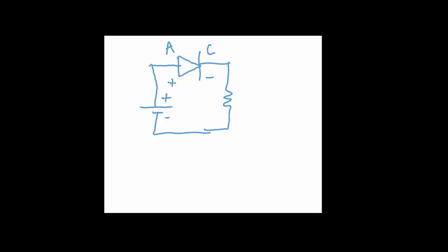The diode will conduct only when it is forward biased. Remember that this is the anode of the diode and this is the cathode. A diode is forward biased if the voltage at the anode is higher. For example, if you apply 5 volts and have a 1 kilo ohm load, the load resistor draws current from the source. In this case the diode is forward biased.